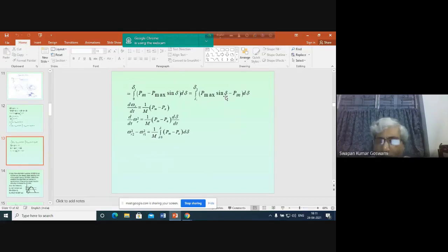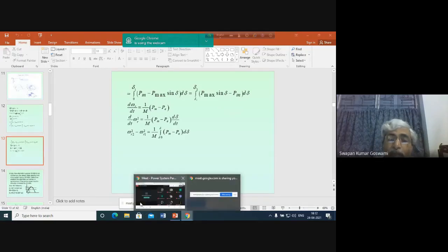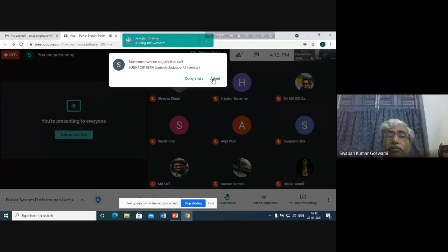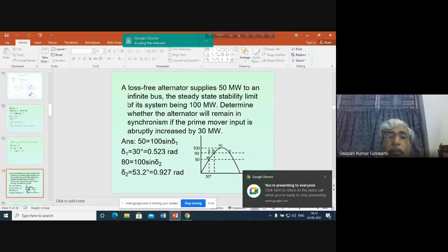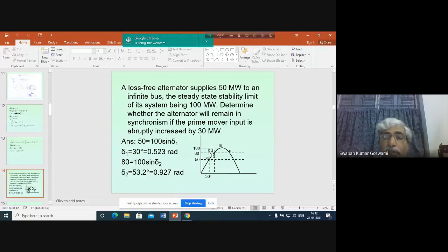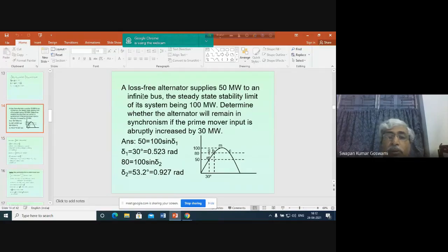We also know, before solving this, that for retaining synchronism or regaining synchronous speed, the stored energy must be the rated stored energy, which is the energy corresponding to the synchronous speed of the generator. So this is regarding the equal area criterion. Now let us apply this to a small example that will help us understand the stability problem in a better way, and understand the criterion further.